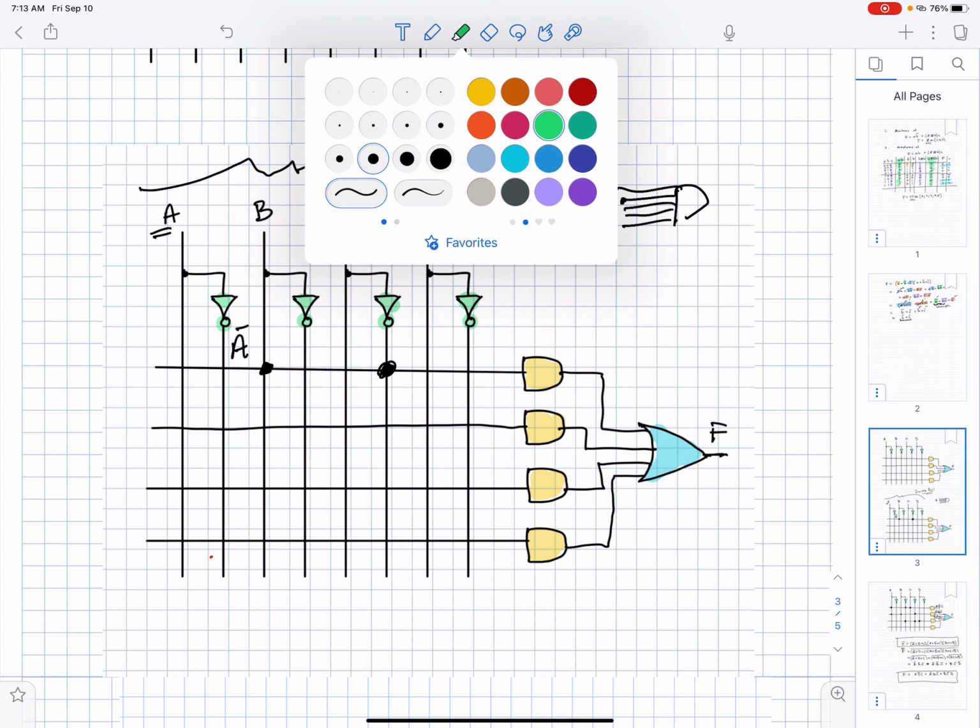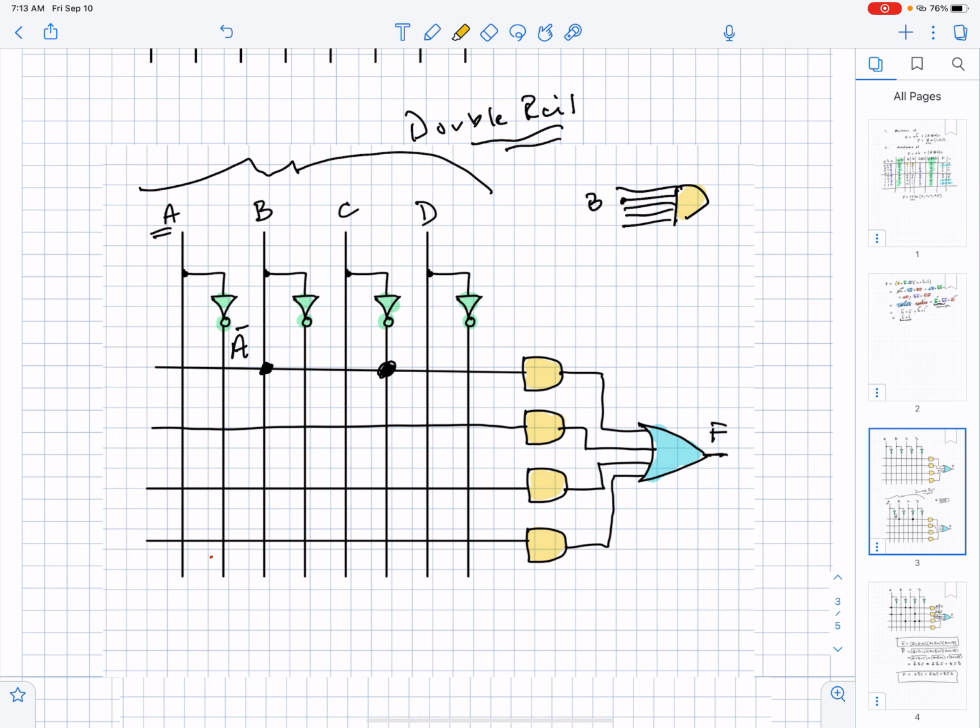In this picture, this gold AND gate actually has lots of connections, but it would be very messy and clouding the issue if we showed all those connections going into that AND gate. So in this particular case, I've got an output where I have the variable B connected and I have the variable C bar connected. Nothing else is connected, so nothing else would come to the gate. So this would be B C bar. I can make some other connections. If I did this,